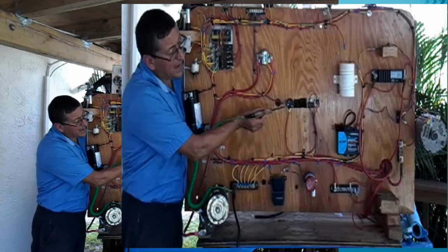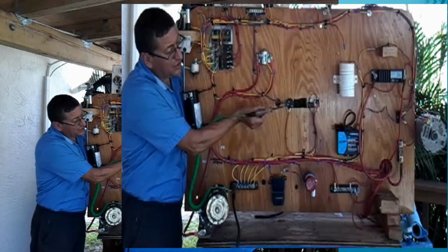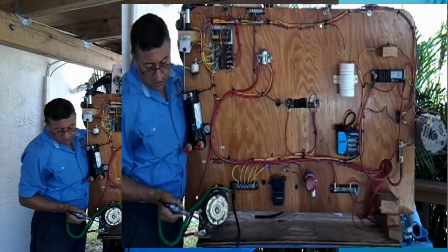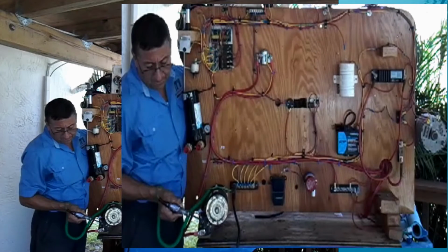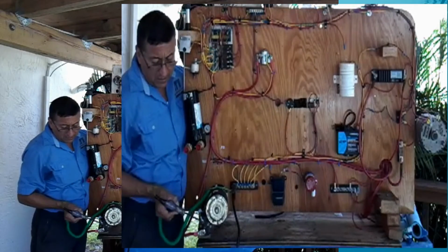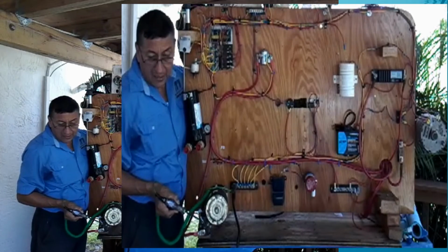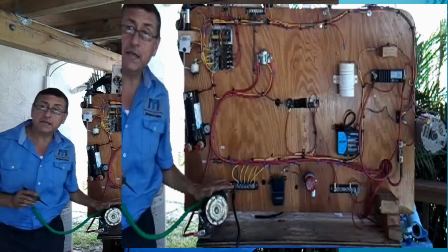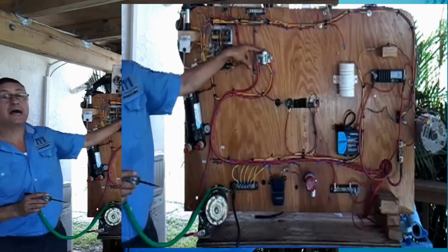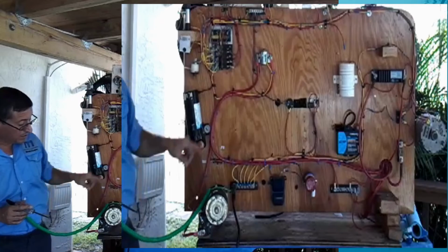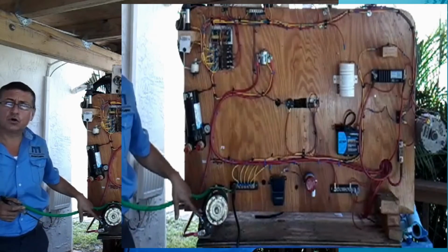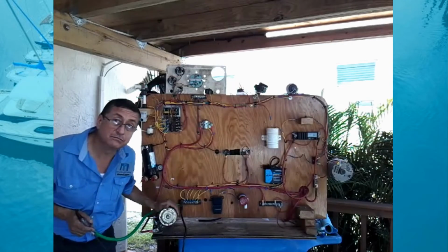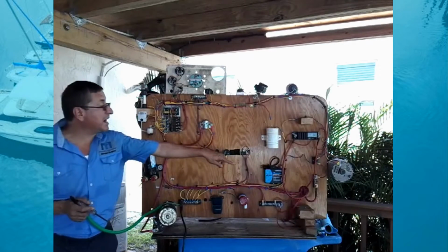When I activate start, the light is on. I don't have power in the second one. When I activate the signal, the power passes to the second one because the signal enters here and the motor is activated. This is a typical example where you combine a relay, the crank relay, with the crank solenoid or start solenoid. The solenoid is located on the start motor, and the relay is part of the system.